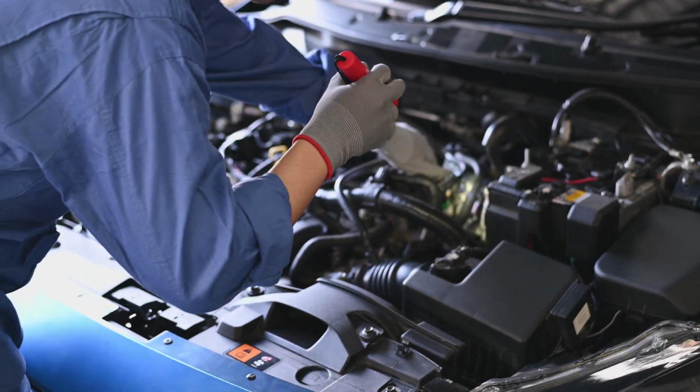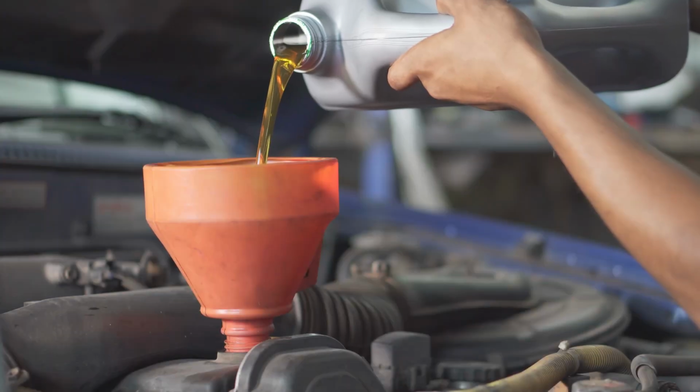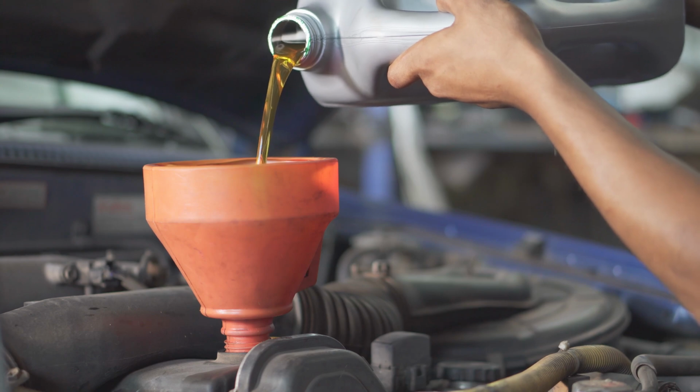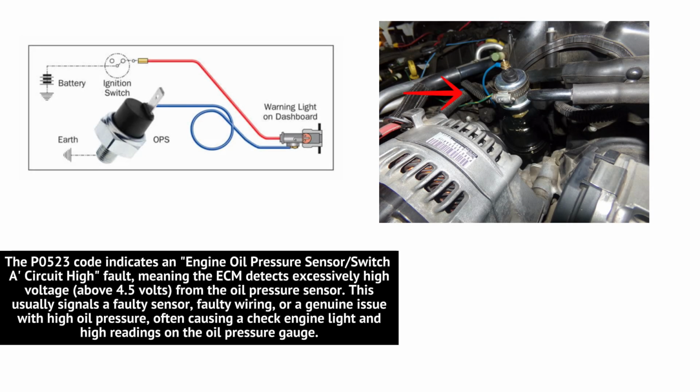The P0523 code means engine oil pressure sensor or switch high voltage. In simple terms, the oil pressure sensor is sending a higher than normal voltage signal to the ECU.